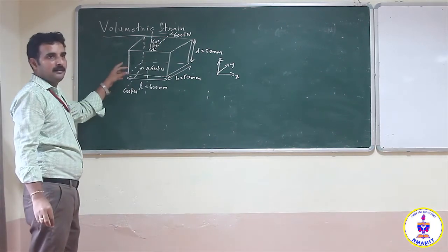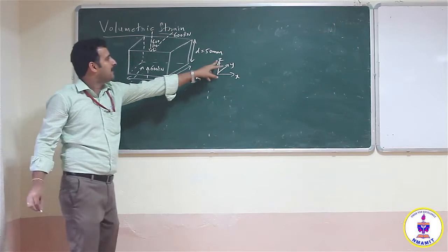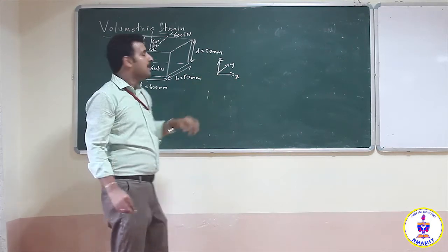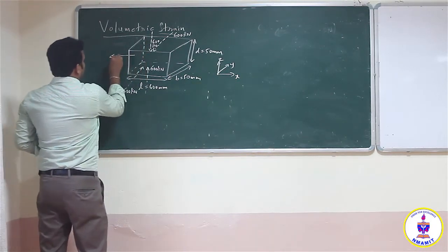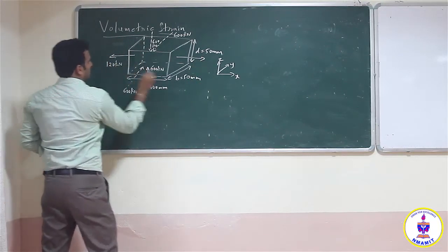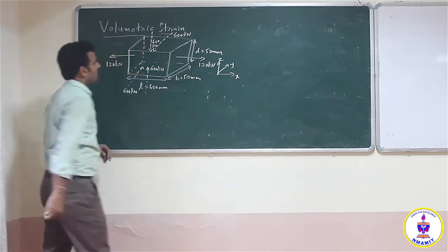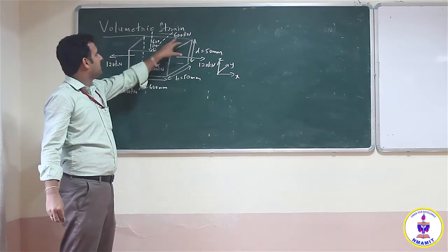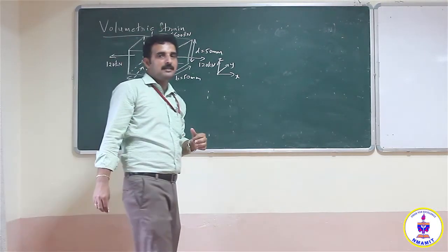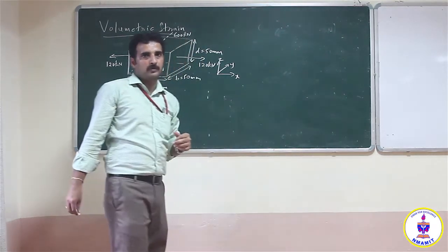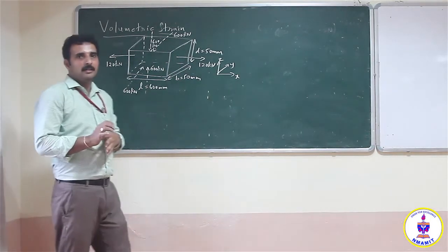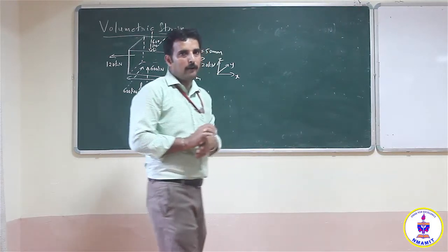Now along X, since they have specified that along Y and Z it is lateral, that is compression, along X it should be longitudinal, which is under tension. So along X it is tensile force, that is 120 kN. So along X it is 120 kN, along Y it is 600 kN compression, along Z again 600 kN compression. So to find what is the change in size and change in the volume. Okay. So first we will find out what is the stress due to these forces.